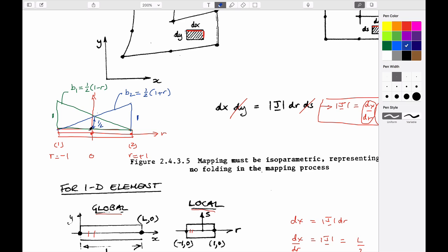So the other behavior that you can see here that's apparent is if you take a section here and you drill down through here, and if you look at this height of this line here and add it on here, it would give you a straight line across the top. In other words, if you add the blue and the green triangles together, sum them up, then they just equal unity everywhere. And so these are the shape functions. We mentioned that they satisfy two requirements. They equal unity at the node in question.